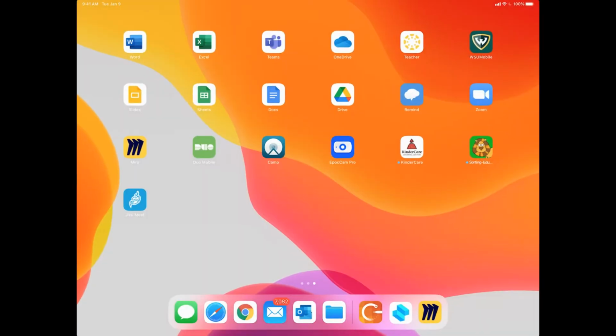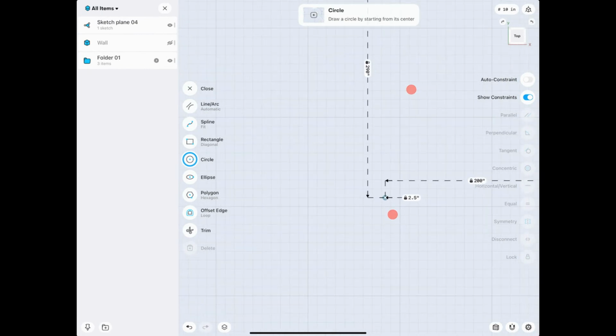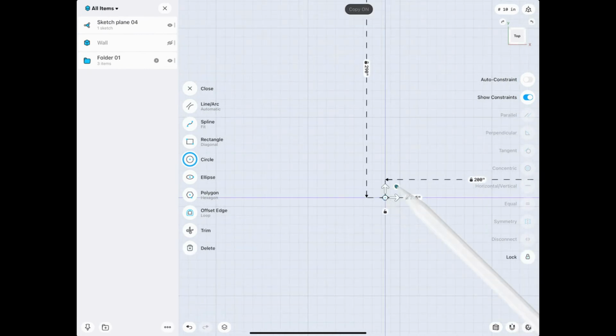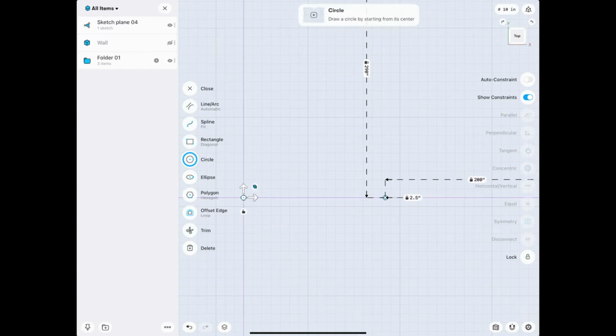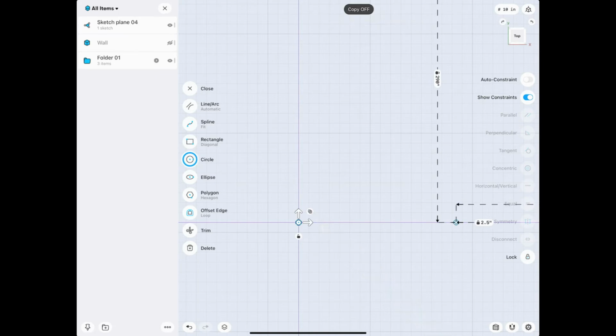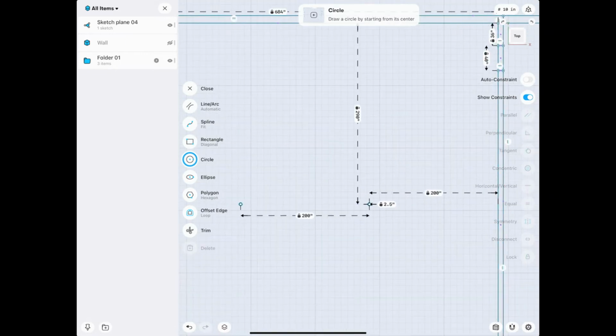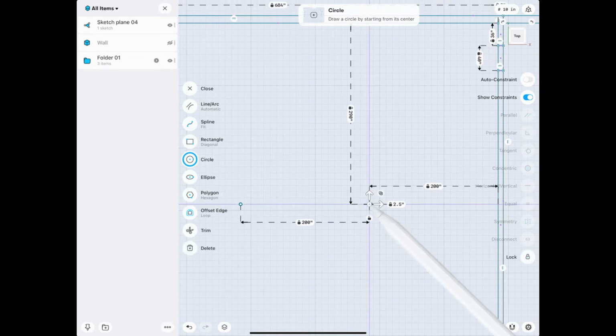Now we would like to make a copy of this, and this is 207 away. So we can tap on the ring, click on this plus icon, move this over, and there we are. Very good. Then turn this off, tap on the ring, tap on this ring, and there. Let's also type in 200. Let's go with even numbers. Okay. So this, I do not want to move anymore, so I will select them and select the lock constraint. So they can't move anymore.